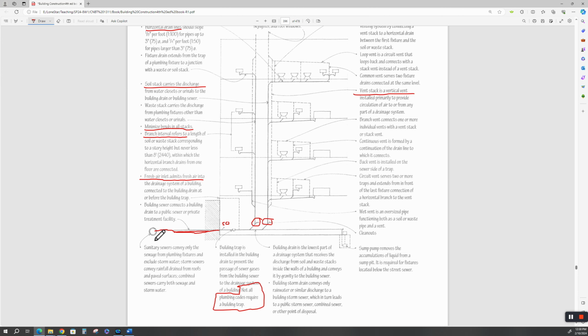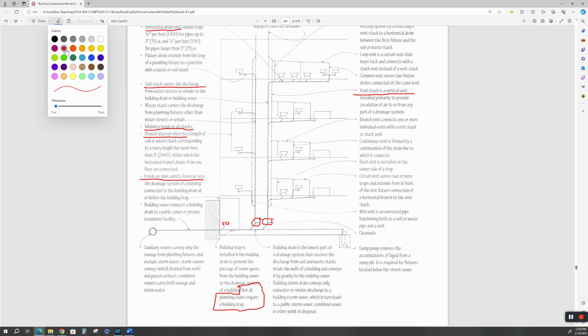Your sanitary sewer, which is gravity fed, and this is really a poor drawing. I'm sorry, I like Ching, but this is not how it's usually done. They don't come into the side of the sewer. What they actually do, and since you're paying money for this course, and I'm an engineer, I'm going to show you really what the thing's going to look like. Here's the sewer, and then they'll have a drop stack that comes off the top, the socket. This is the flow line of a sewer pipe. The bottom is the flow line. The top is called the soffit,